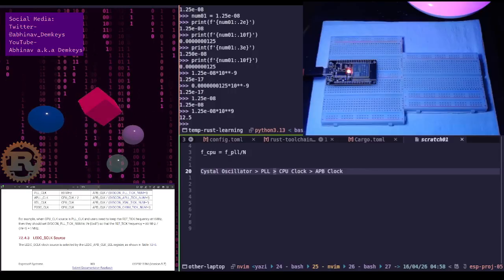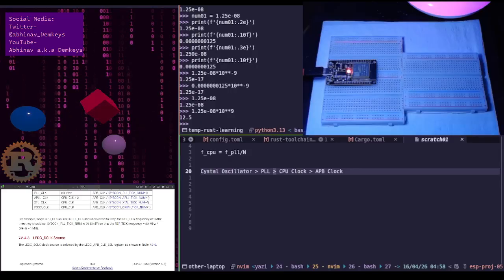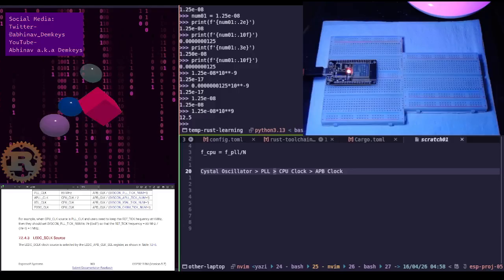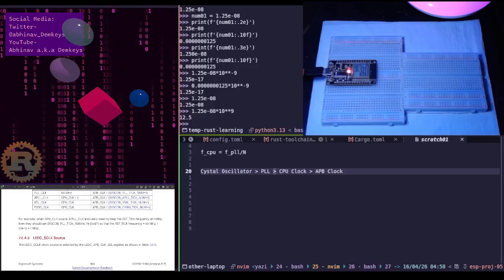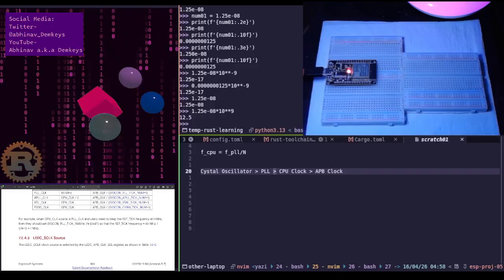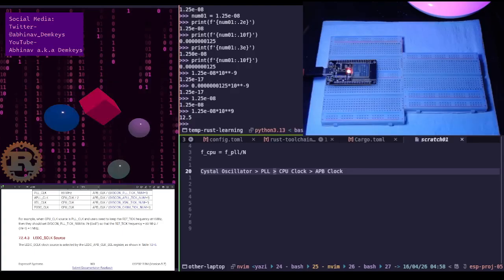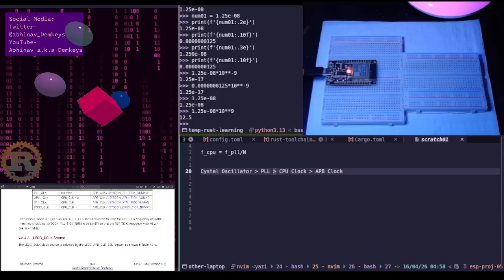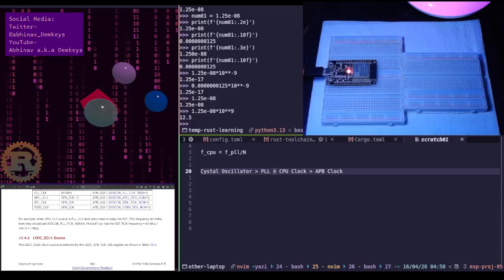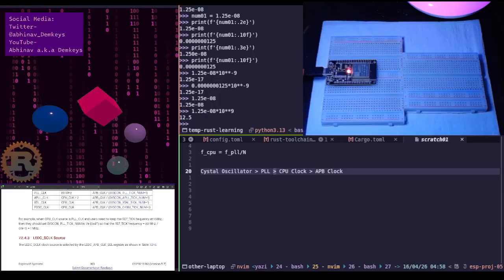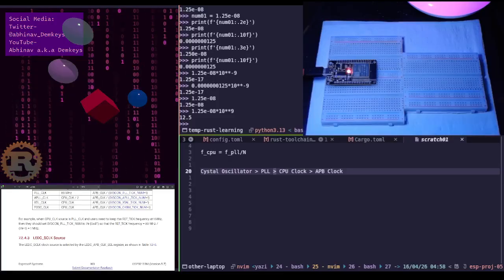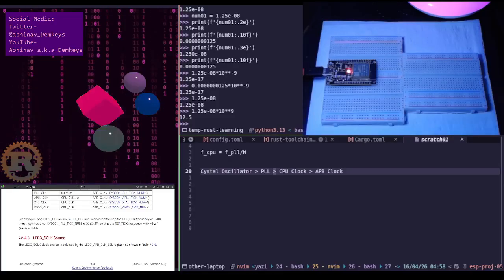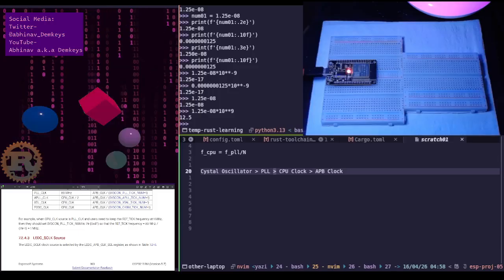The independence nuance, the logic. The reason it was described as avoiding dependency is because of how the ESP32 handles its dividers. In most microcontrollers, if you double the CPU speed, the peripheral speed doubles too. But the ESP32 has an automatic dynamic divider.